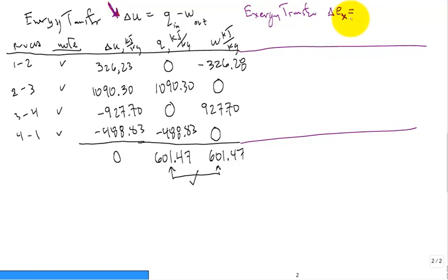Okay, well, you can have the exergy transfer. I'm going to write it like this. EX transfer with the heat. That would be coming in if the heat was coming in. If the heat was negative, heat transfer is negative, then we'll be taking it out. Then we're going to have minus the exergy transfer with the work. If the work is positive out, then that's an out. So we keep a negative sign on this exergy balance equation.